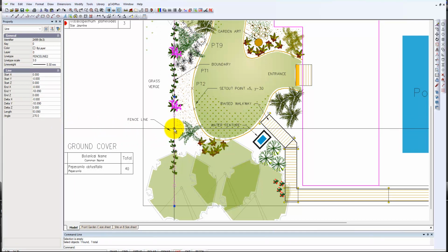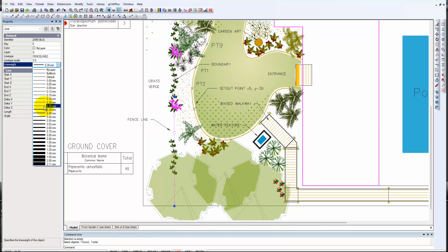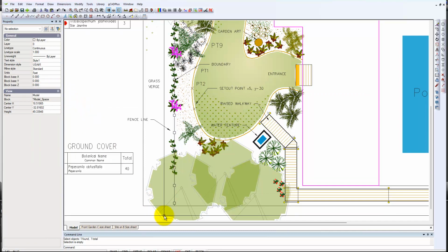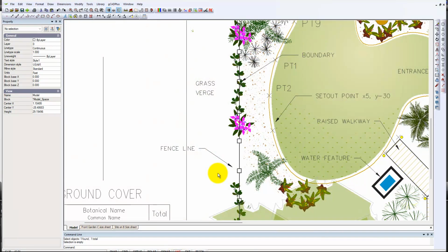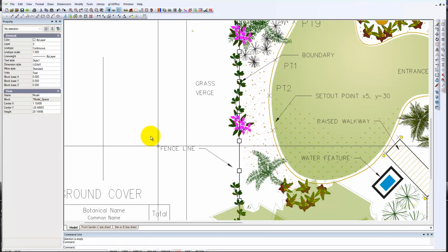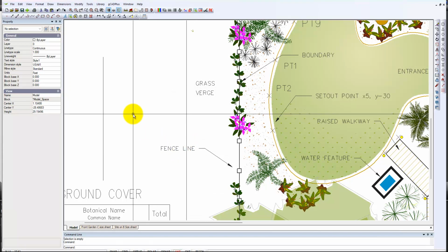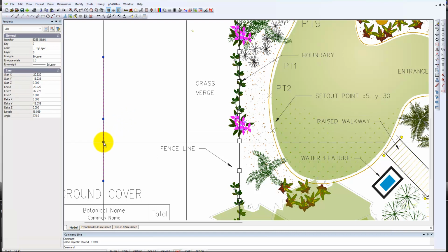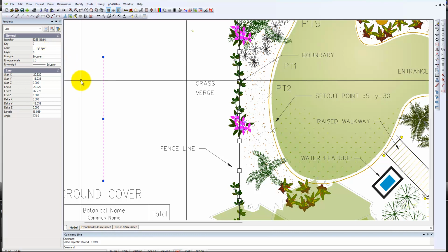If you think that's a little heavy, just wind the thickness back. But if we go to 0.25, there won't be a difference between line weights on or off. So our advice is to leave formatting and line weights set to 2.5 and leave it set to draw by layer and apply. Things can get quite complicated if you start to mix up. For example, this line has been drawn inheriting color by layer and so on.